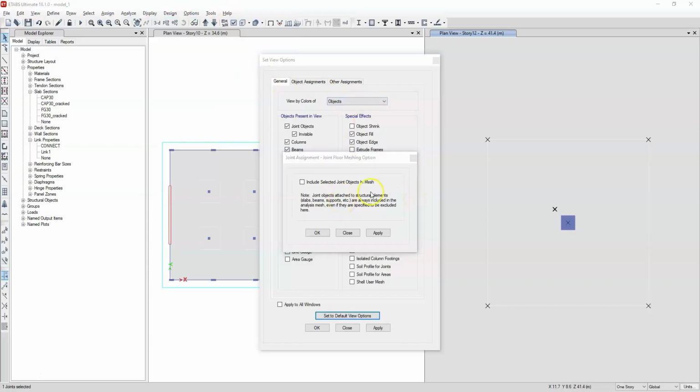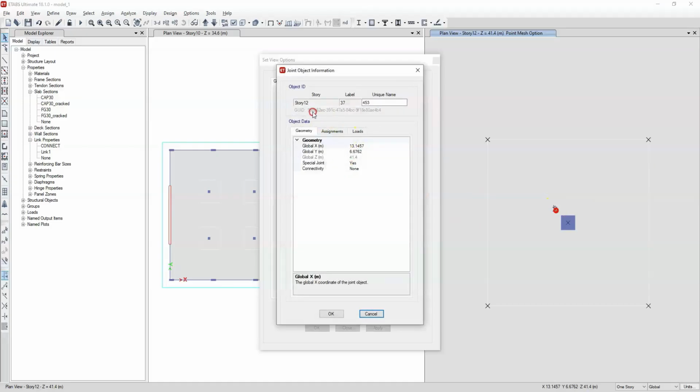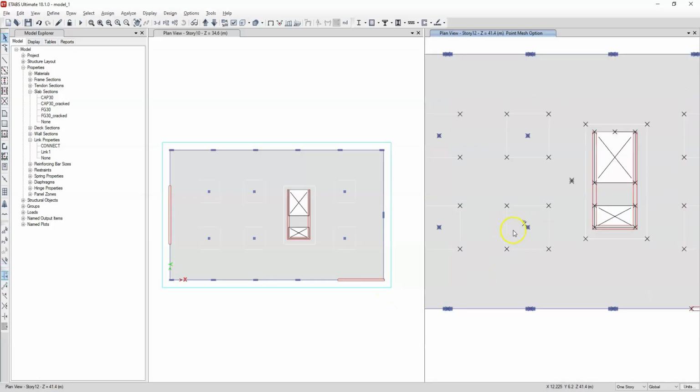An important aspect is that we have to include this joint in the automatic meshing of the elements. It is very important that this property is assigned because this element should influence the mesh. It could be left without influencing it, and there would only be the possibility of simply being used to distribute loads. But for consistency reasons, for the exact application of the forces and to guarantee that there are no problems with mass undefinedness, it is appropriate in our cases to ensure that the newly added points have this property well defined. That is, to guarantee that this point participates in the automatically generated mesh.